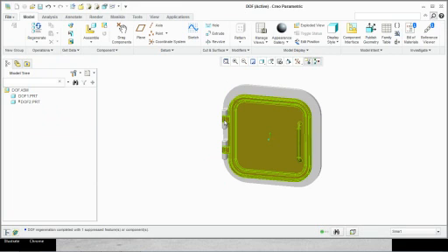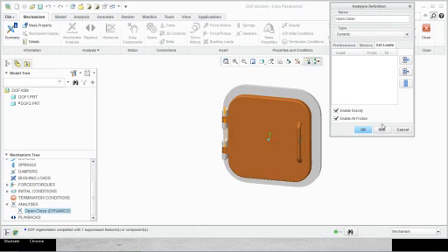See that? No motors, no external loads. I just go ahead and run it. Stays where it is. Notice that in our measures we can see there is 1 degree of freedom, but there are 4 redundancies. See that? Now, what is this redundancy?